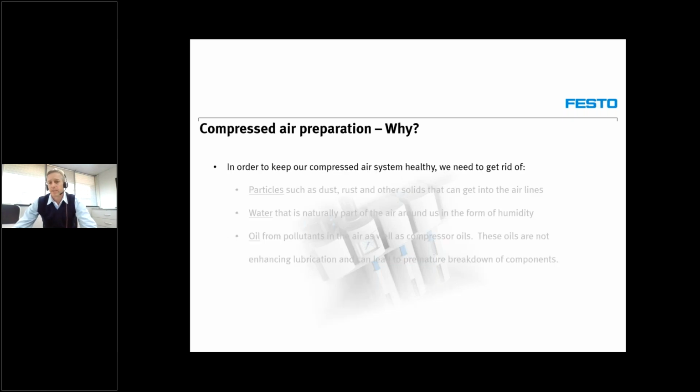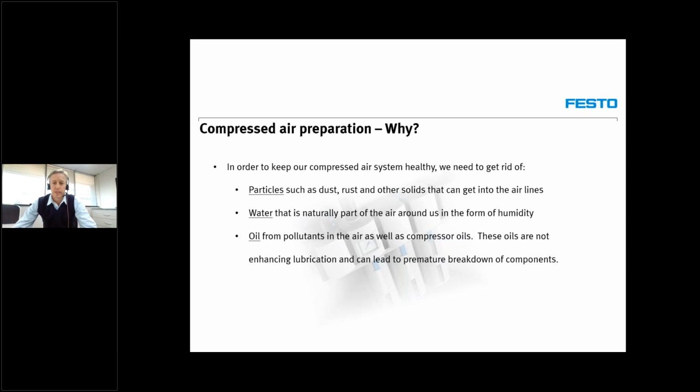Now, in order to keep your compressed air system healthy, we need to get rid of particles such as dust, rust, and other solids. We need to get rid of water that is naturally part of the air around us in the form of humidity. And we need to get rid of oil, which is coming from pollutants in the air, as well as from compressor oils. Please note that these oils are not good for lubrication in the pneumatic systems and can lead to